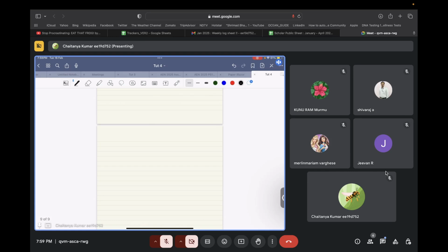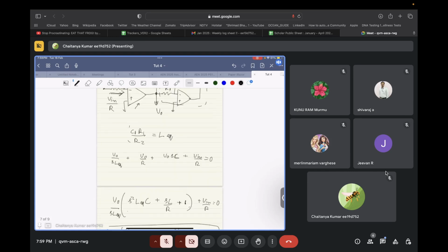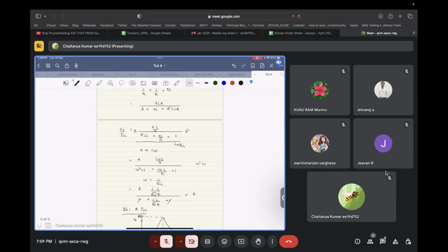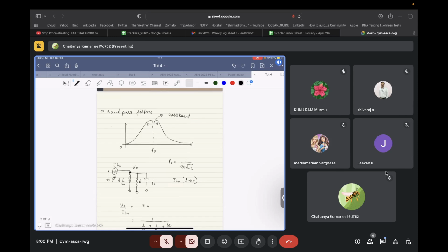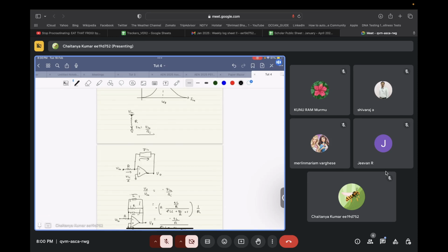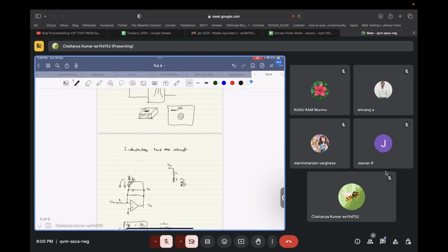Till now we studied one kind of circuit, right? So let's see from where we started. We started with the basic concept that we wanted to push a current into this parallel RLC network, and to push the current, we took the way of pushing the current to a virtual ground. Now this is not the only way.